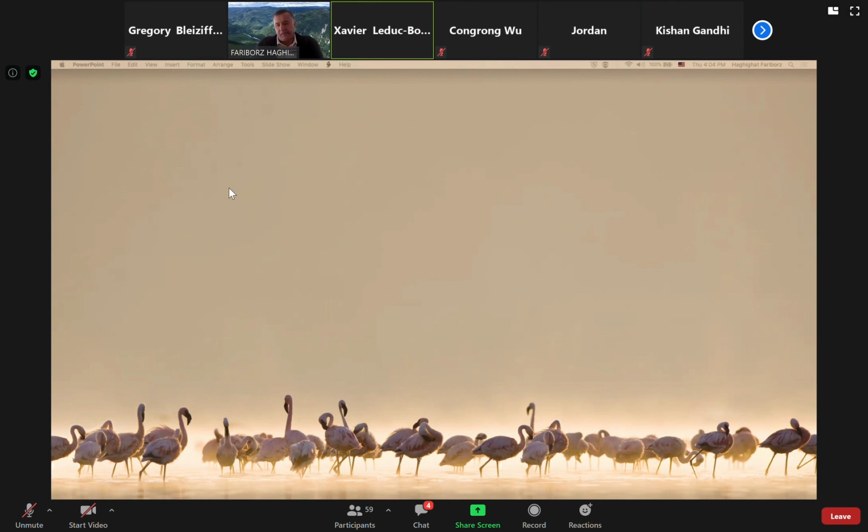The heat generation from infiltration also includes other variables like Q. Is it possible? Well, there's no heat generation by infiltration. Yeah, it's varying, depending on the temperature inside and temperature outside. So it should be an equation. Energy exchange. There's no heat generation. There's energy exchange between inside and outside, and that's due to the infiltration. If your building is leaky, it brings some air from outside to inside. Therefore, there is some energy exchange between inside and outside, and that's the case, yes. Okay, thank you. No problem.